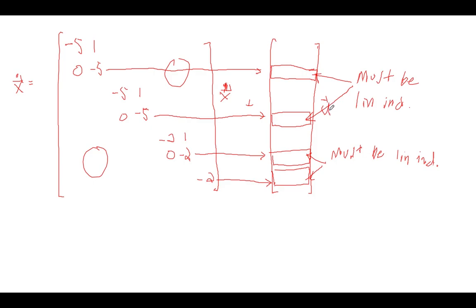By adding another input to U, we'd add another column to the B matrix, and you'd want the number that gets added here to be different than the number that gets added here, in a way that now these two rows are linearly independent. So effectively, we'd be adding a new actuator to our system that affects these states differently than it affects these states. And that's the way we get to controllability. So unlike the other tests for controllability where it's a very yes or no answer, it is or isn't controllable, this test in Jordan form actually lets you look at how you would fix your system if it's not controllable, or at least gives you ideas of how you might fix it.